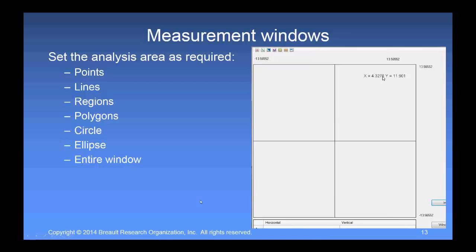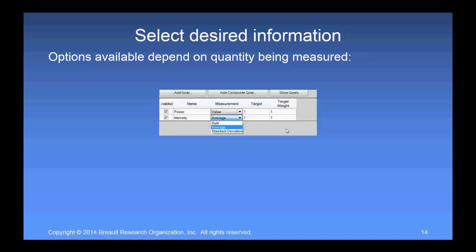And by default, there will be a simple adjacent pixel averaging applied because, as we know, there's lots of statistical noise in illumination designs. But you can also apply different types of averaging to the data if you prefer, and that would be listed in this drop-down area here. But again, I should have shrunk my window down to show, but we're going to see the whole setup in a couple of minutes. So if it's cut off here, don't worry about it. You will see it in a few moments.